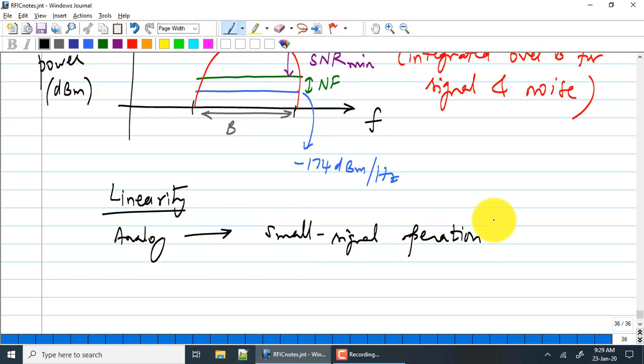Imagine some of you might be audiophiles where you have used speakers, specialist speakers and so on, listening to music or something else. If your volume control is very low, the power going out is very low, it will sound very clear. As you keep upping it, it will degrade slowly, because the second order term is missing, and normally the second order term in the Taylor series rises faster than the first order term. Eventually it will degrade so much that there will be a